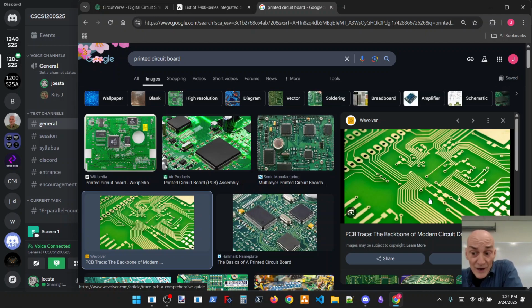And then, if you really wanted to, we could take multiple of these boards and stack them up and create a multi-layer board. Essentially, stack them up and glue them together. So, typically, your motherboards and things in computers, which are much more complex boards, are probably multi-layer boards. But that's the plated through holes, the vias, so we can connect them together. What else can I say about that? Do you have any questions?